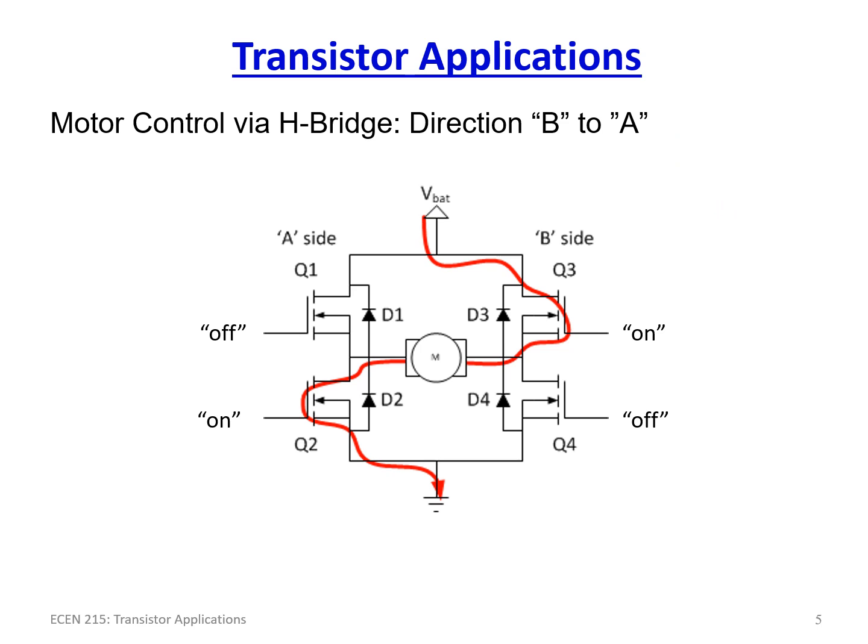Now, the one thing that you can never have happen is this become on and this become on at the same time. That is a mega no-no. I hate to say it like that, but you do not want that to happen, because when that occurs, you short out the H bridge and cause current to go straight from the battery to the ground, bypassing the motor completely. And if you do not have a fuse here, which you usually will have in the circuit somewhere, you will cause your battery either to explode or otherwise melt terminals or melt wire.